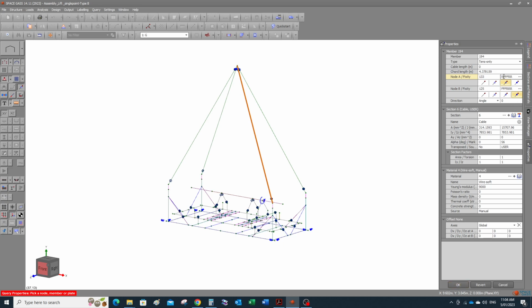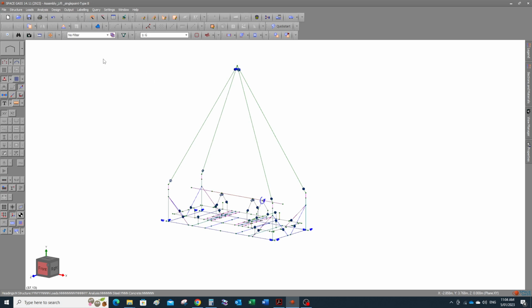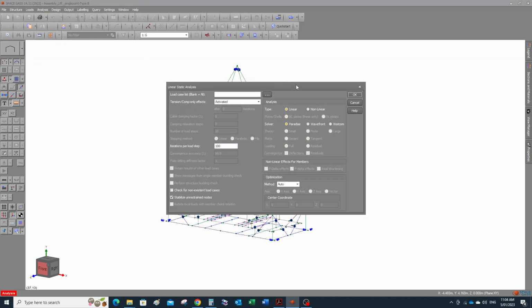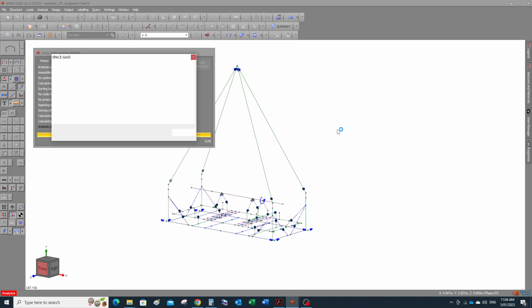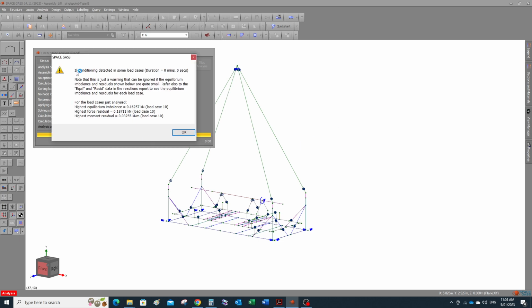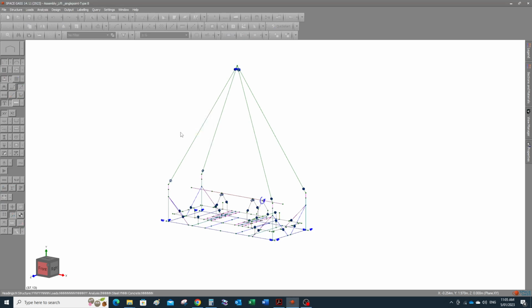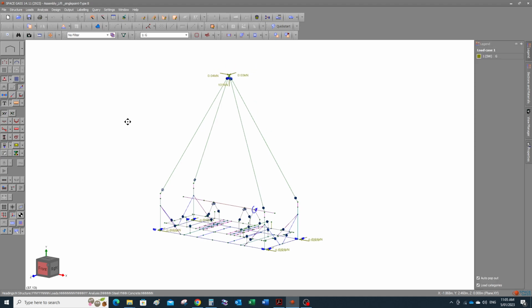So you see what I've done, this is for the X deflection or X stiffness of the member. I release that for one of them only, and we'll analyze to see what happens. The first effect is that it's ill-conditioned. We cannot escape that, but we have to interrogate the model to see how bad it is.